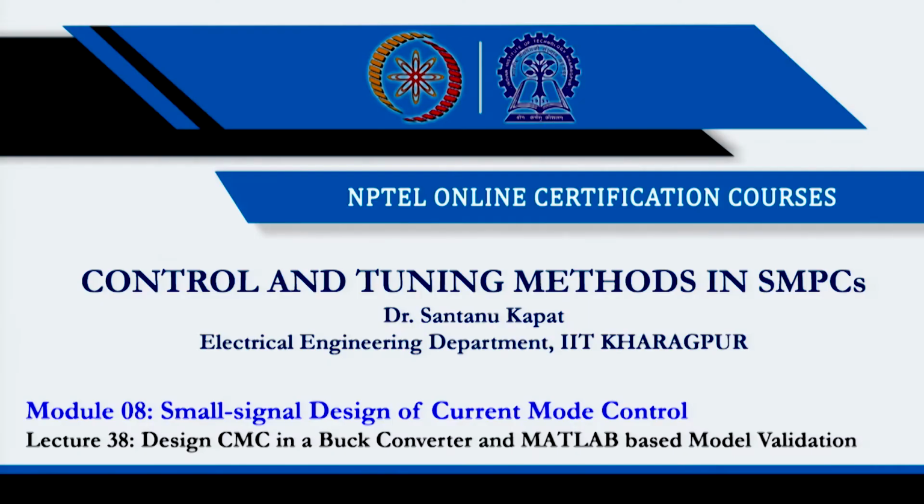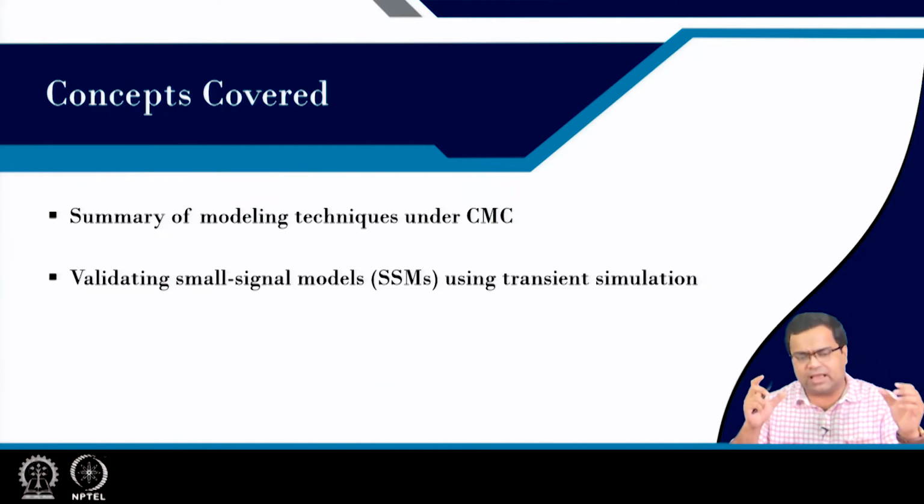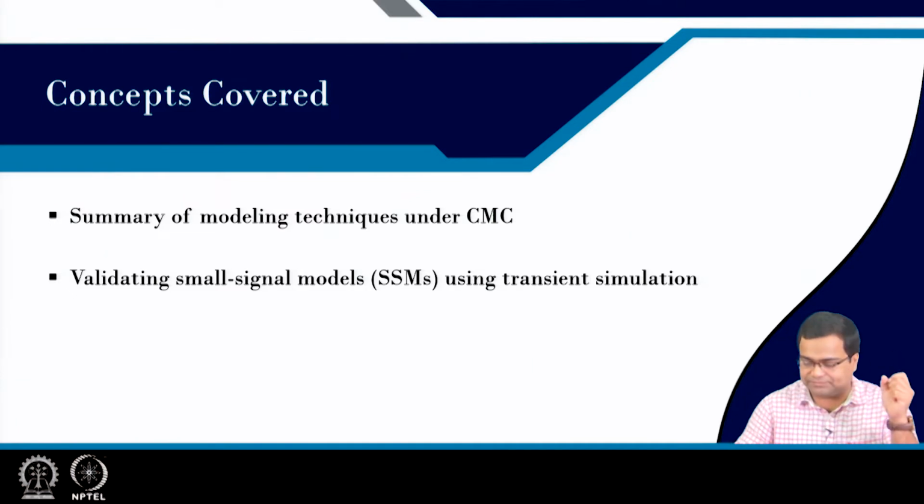In this lecture, we are going to talk about design of current mode control in a buck converter and Matlab based model validation. So, in this lecture, we are going to first summarize different modeling techniques under current mode control. Then we need to validate the small signal model using transient simulation, Matlab AC transient simulation. Here we want to validate the closed loop converter.